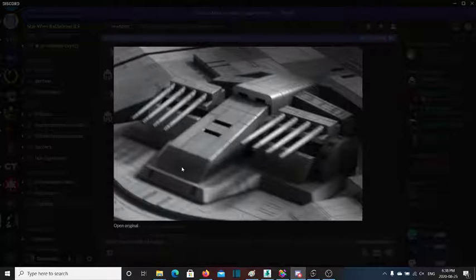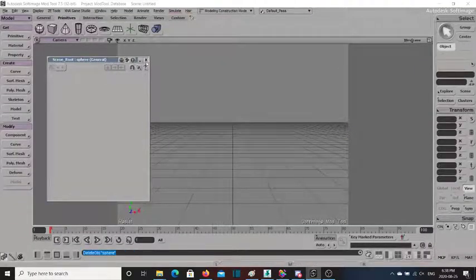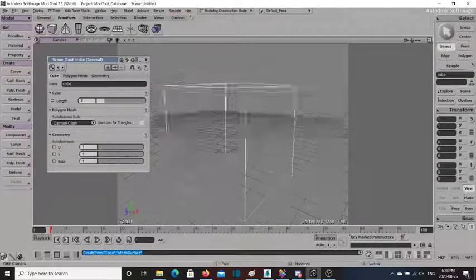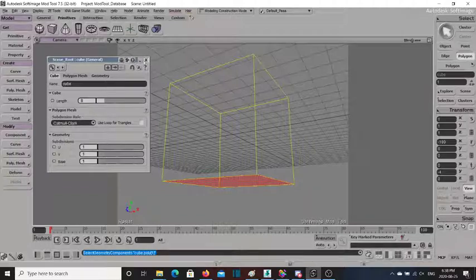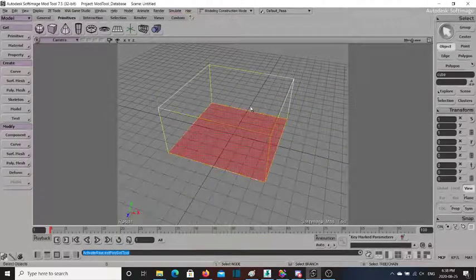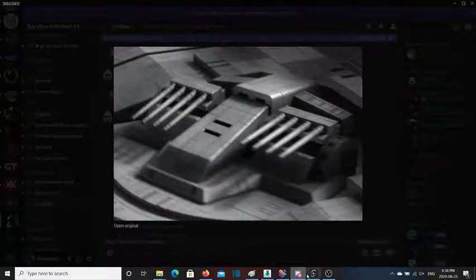So first, I'm going to create this bottom layer here as a plus sign. So I'm going to go into Softimage. Sorry, clicked the wrong primitive cube. I'm going to extend it downwards. Now I know that I want this at 0 position, so I'm going to go Y0, extend this over, and I want my depth to be about there, right?